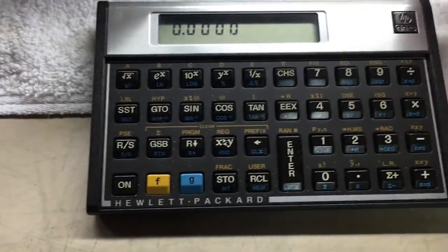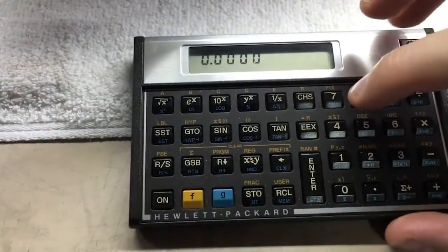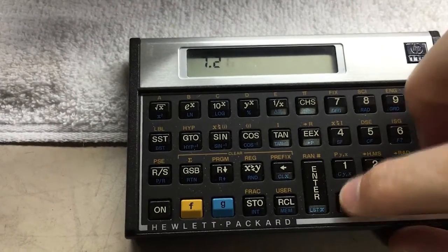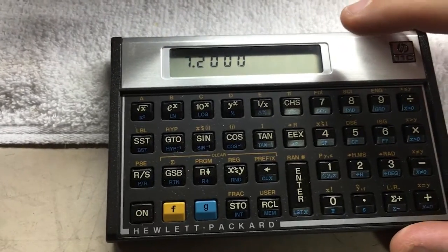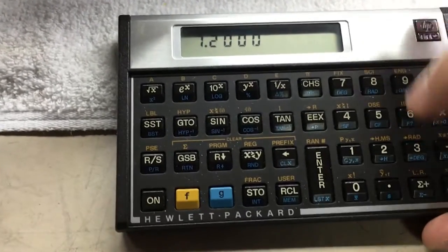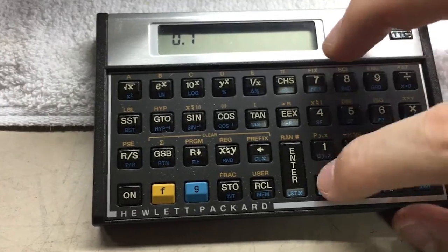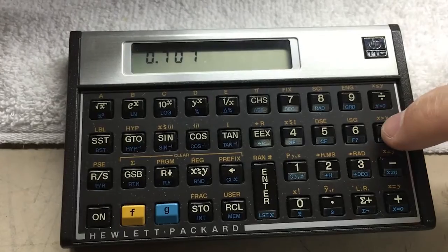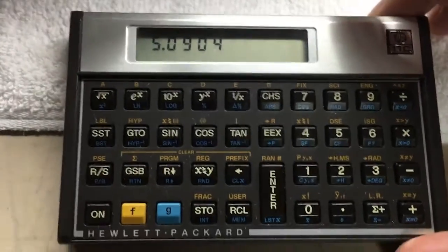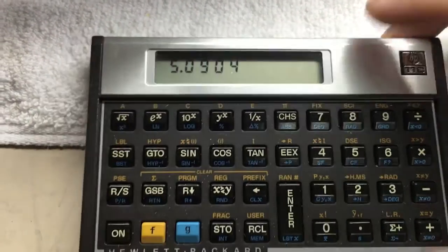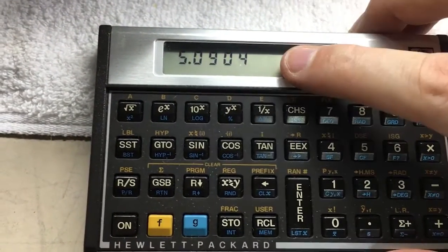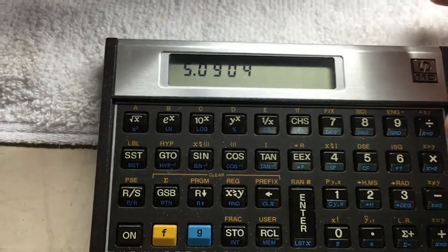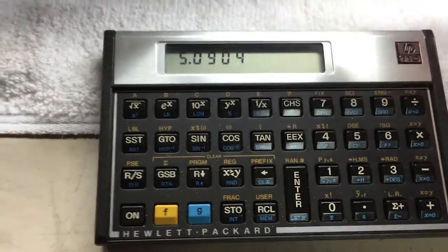They use a function called reverse Polish notation, so if you try to follow what I'm doing, it'll probably lose you. But basically, we're going to go here, and on this thing, we're going to say we've got 7.20. We're going to enter that into the register, and then we've got to multiply that times 0.707. We're going to enter that into a register, and we're actually going to hit the times to enter that one. And what does it give us? 5.094. So what is that? Remember, the peak voltage times 0.707, that gets us to 5.09 volts, right? RMS at this point.